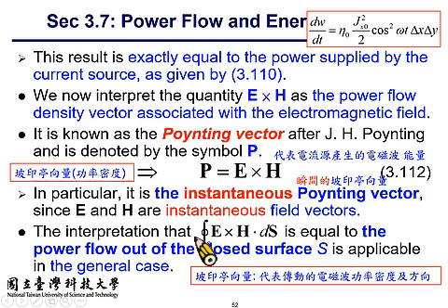Suppose you have a dipole, as I already described, and we know that due to the presence of vibrating currents on the dipole, it shall produce E and H field in its neighborhood, and they shall propagate outward and deliver energies to remote places in the form of electric and magnetic field, which is also in the form of Poynting vector.